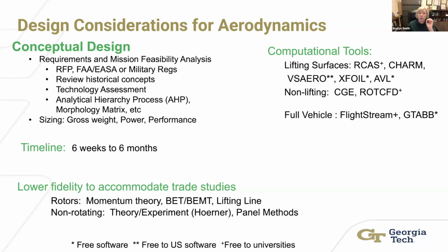All right, so your goal here is to freeze your concept. This is when you're looking at all those different concepts. You want to freeze the concept. You've got an idea, you know, single main rotor, quad rotor, tail sitter, whatever you're planning to do. That's the concept that's frozen here, not the details. All right. This is why you don't need all of the RANS CFD. You're not there yet. You don't know what your configuration actually is yet. Okay. You just have a concept in mind.